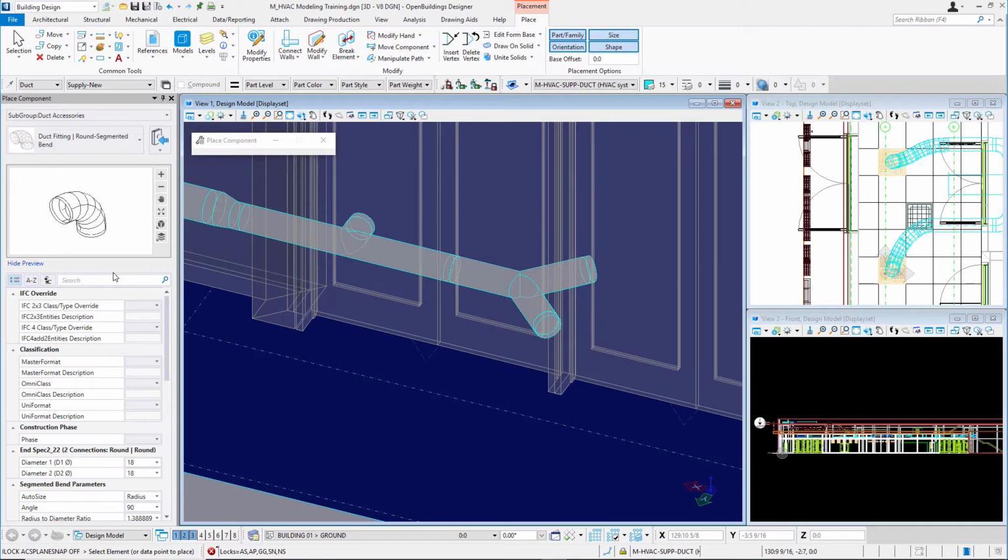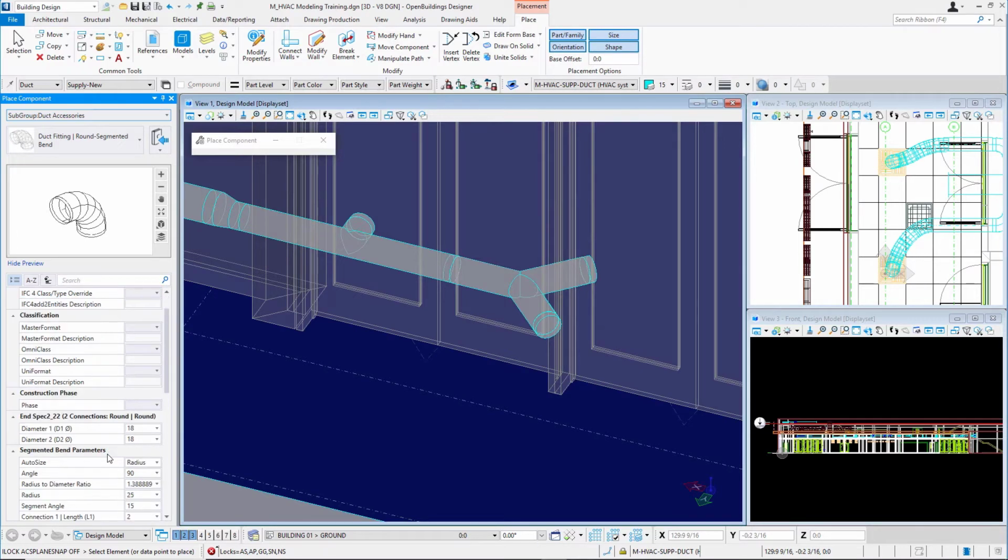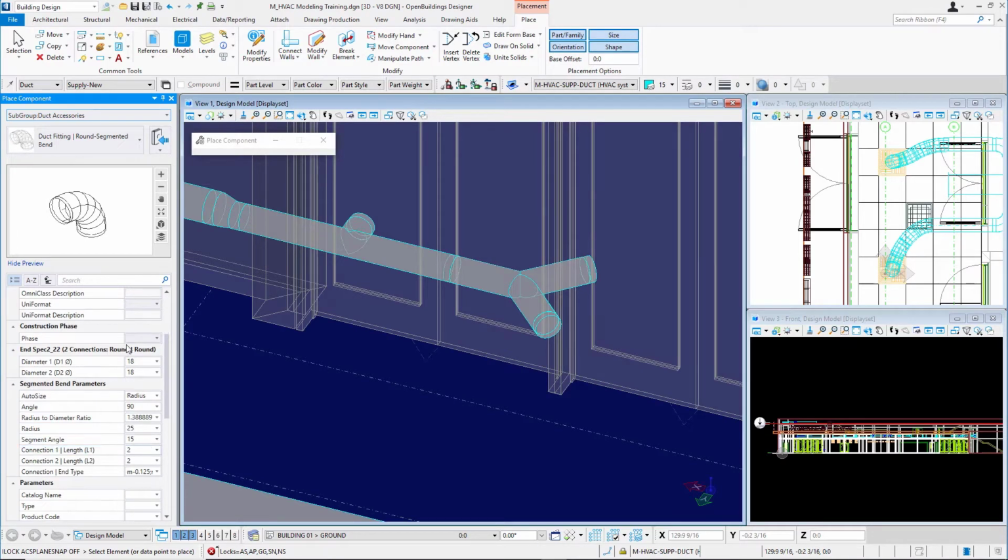Taking a look at these context menu options in the property panel. So the property panel, we see our various data group properties in different categories. If we scroll down some, throughout the video series, I keep saying, well, I'm going to set my construction phase to new construction. That's just an example of one of the property values. And I do want to turn my shape off up here, so turning the shape off in the ribbon interface.